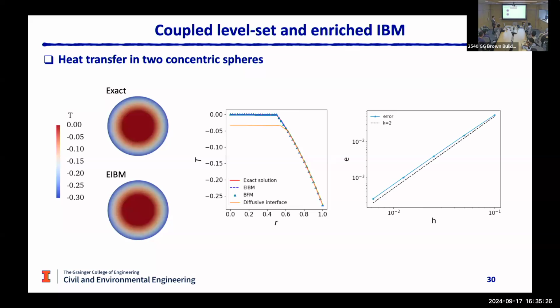Because I know that many people don't trust modeling because sometimes they say it's not reliable. However, this is because people don't perform mesh refinement study. So if you want to ensure the reliability of your model, you often need to perform a refinement study to make sure that the results are converging.